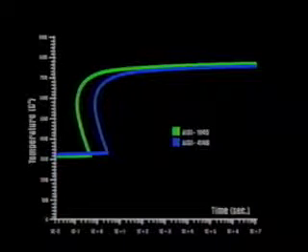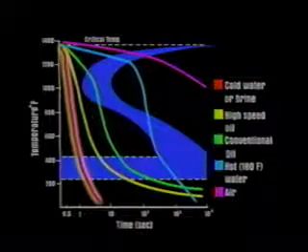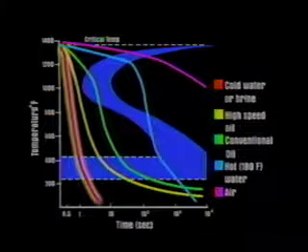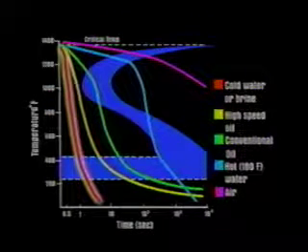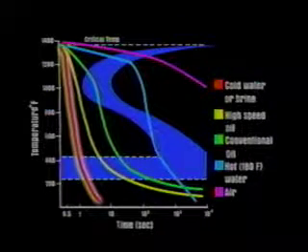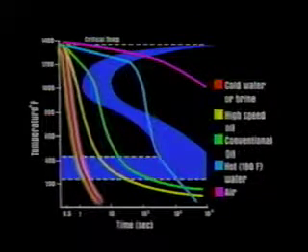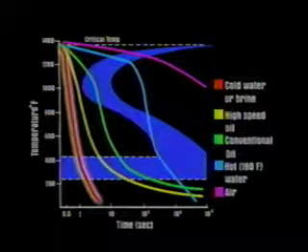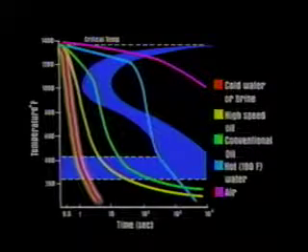This is confirmed by comparing the hardness obtained when identical pieces of 1045 and 4140 steel are immersed in a given quench oil. The ability to through-harden steel is not only dependent on the hardenability of the steel, but is also dependent on the dimensions of the component and the quenchant selected. For example, cold water or brine, which are fast quenchants, are often selected for more difficult to harden plain carbon steels in order to maximize the formation of the desired martensite microstructure.